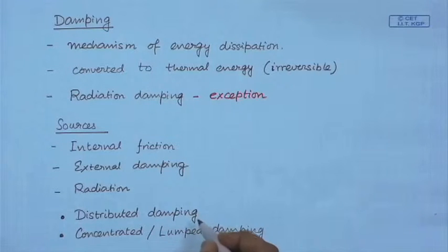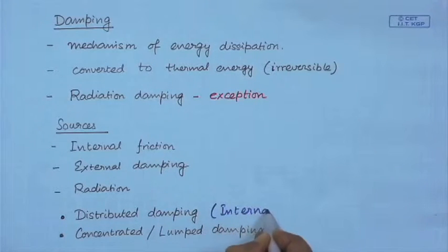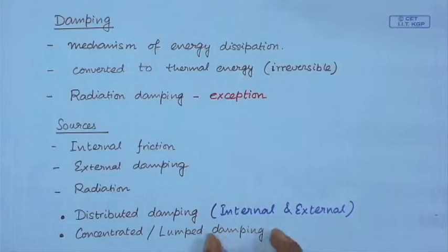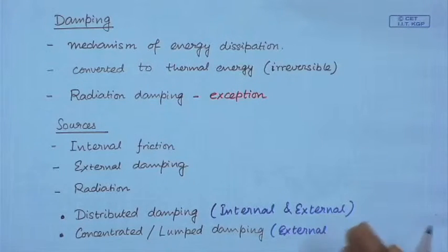Now, these internal dissipation and external damping because of fluid are distributed damping, while concentrated or lumped damping can occur in external damping when we attach a lumped dashpot or damper at a particular point on a structure.